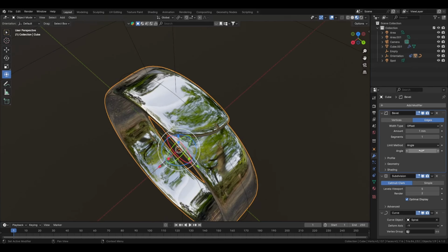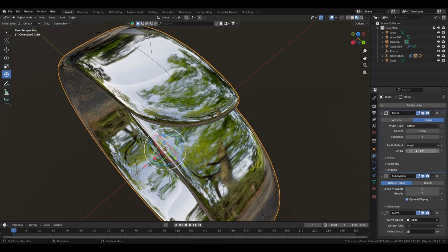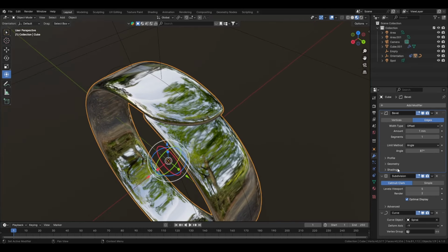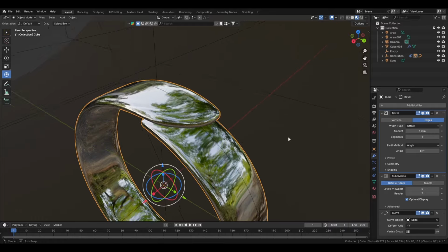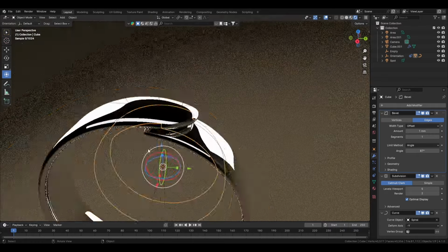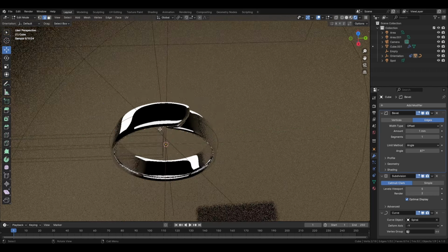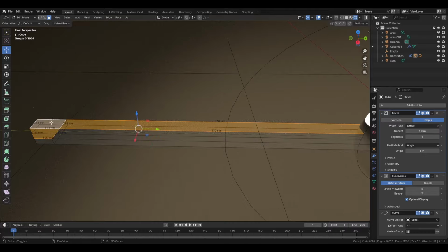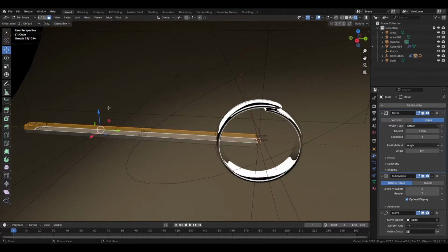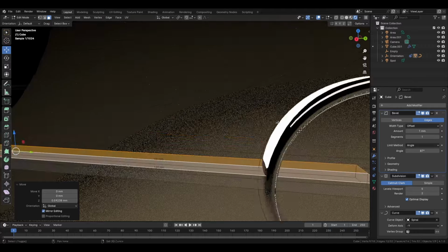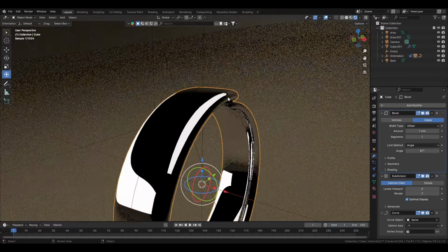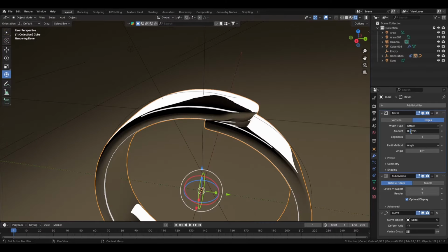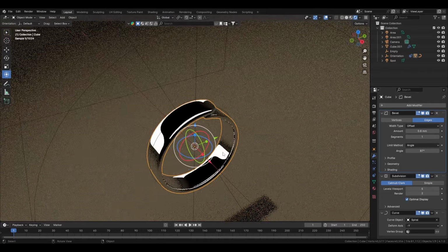So you can move this up, but don't go over 90 degrees, otherwise it's going to modify everything. So I don't know, put it at 87 for example, or something close. Then we said we want it thicker, so we can select all the top parts here and bring it a bit thicker like this. And maybe it's a bit too round, so we can change this to 0.8. Alright, so that's good.